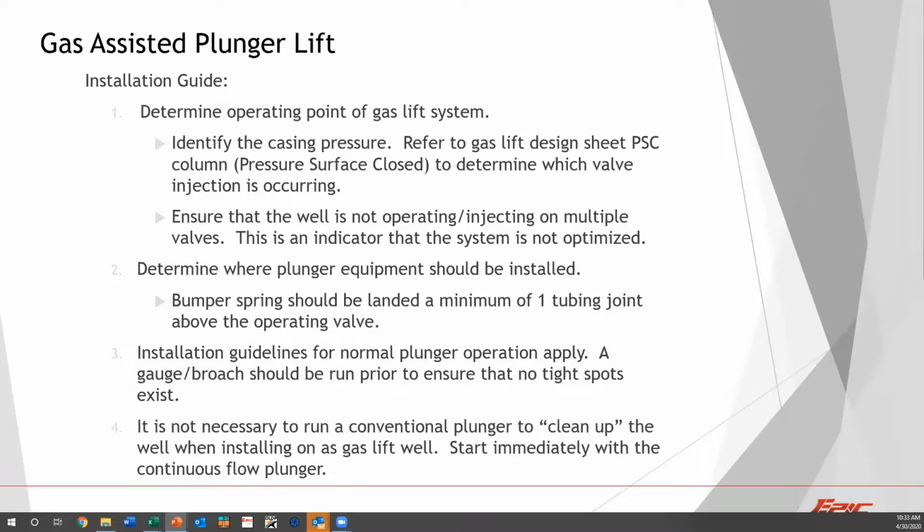The biggest difference is we do not need to run what we refer to as cleanup cycles. This is where we take the plunger and run it with no afterflow, and the purpose is running it like a little swab rig, unloading all the excess fluid from the system. But because this well is a gas lift well, it's not going to have liquid loading signs. We don't have any excess fluid, so we can just start immediately with our bypass plunger operations.